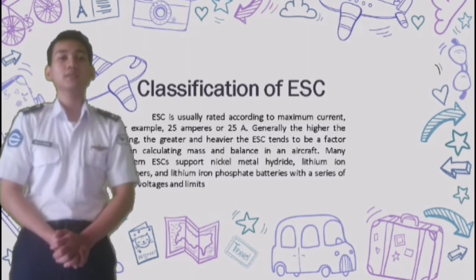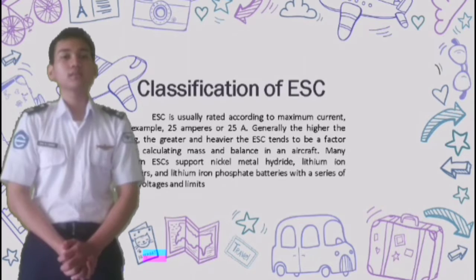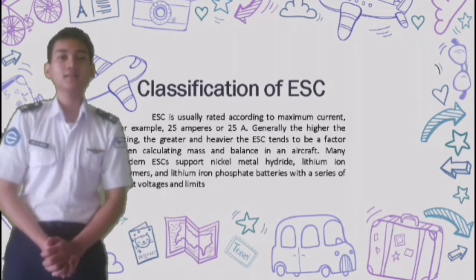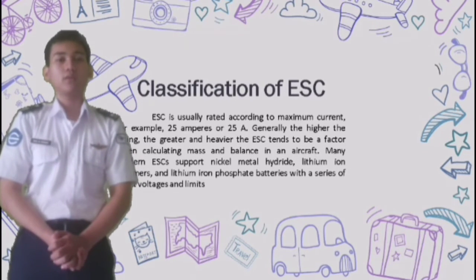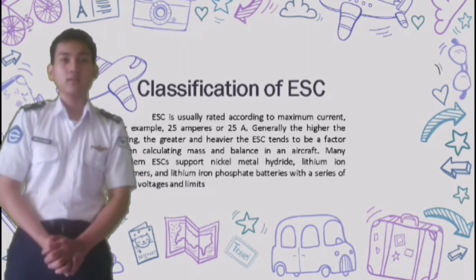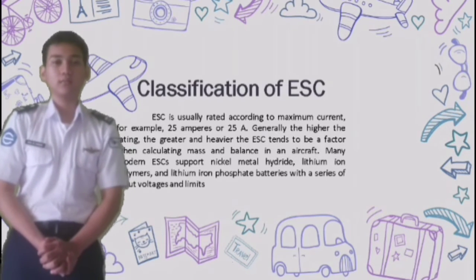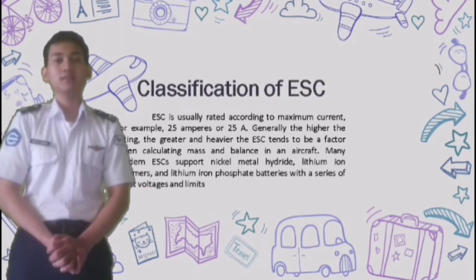The higher number of cells connected will result in a reduced power rating and hence the lower number of servos supported by integrated BEC if using a linear voltage regulator. A well-designed BEC using a switching regulator may not have the same restriction.